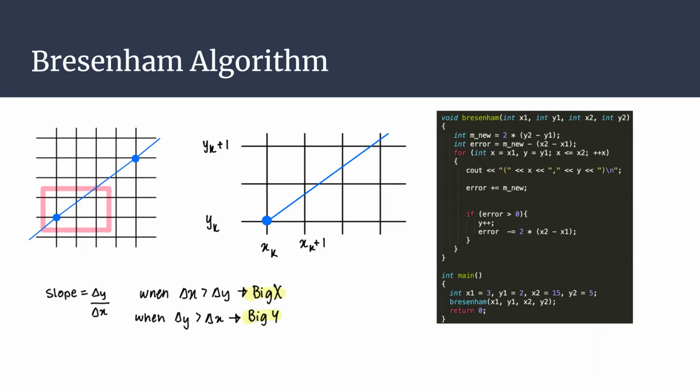So our next task was one of the more complicated ones. This is the Bresenham line drawing algorithm. It's essentially an algorithm that can draw a line from point A to point B, outputting each individual pixel that it has to traverse to get to the second point along that line. Now, this is specifically designed to be heavily parallelized, so there's no multiplication or division involved, and we were able to get approximately 1 pixel per clock cycle, which is, for this project, as good as we can get.